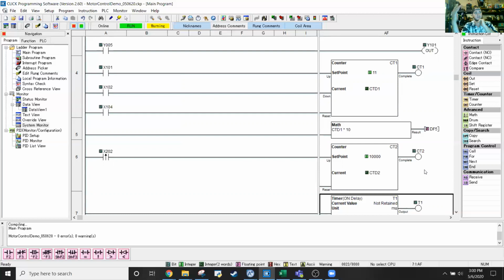And so what you do is you use that signal to figure out rotational or linear positioning. So rotational of the motor, which if it's hooked up to an actuator or a conveyor belt or something, you can then calculate linear positioning of that actuator or of the conveyor belt. So what we've made is a super unsophisticated encoder, which is basically 1 count per revolution.